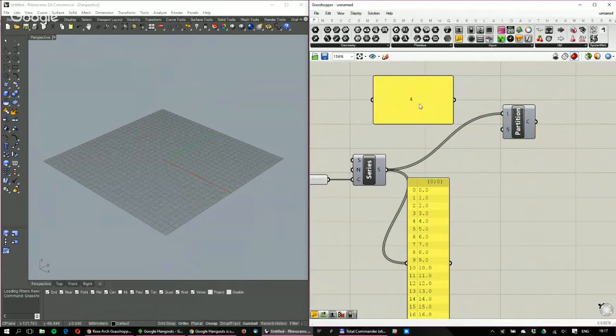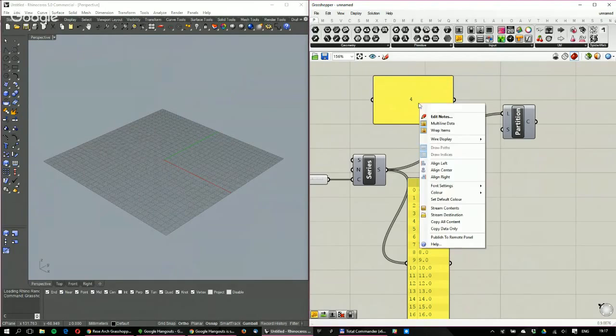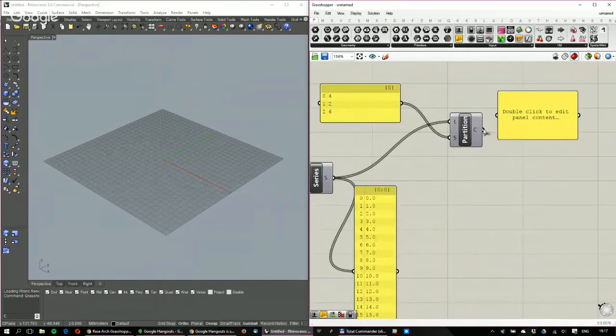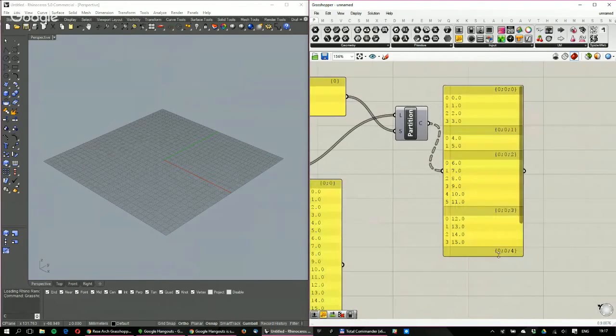If you are using a panel to specify a list of values, you need to deselect multi-line data, which means if this is on by default, the data that you're entering is one piece of data because it can be multi-line. So that's one piece of data in multiple lines. If I switch it off, then each new line is a new piece of data. So if I plug this here, then we end up having a couple of lists here.